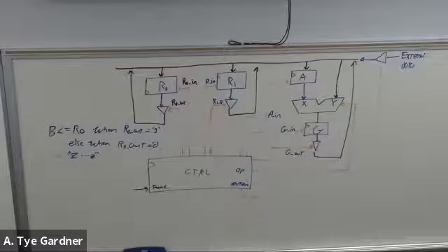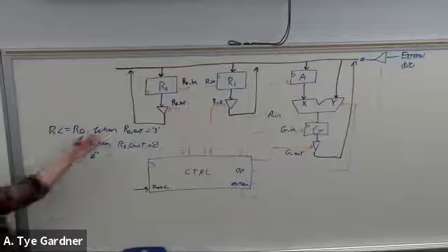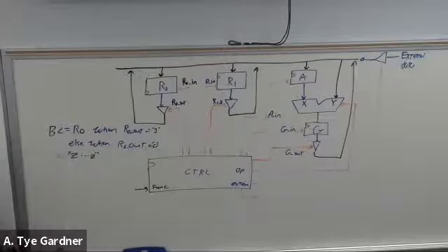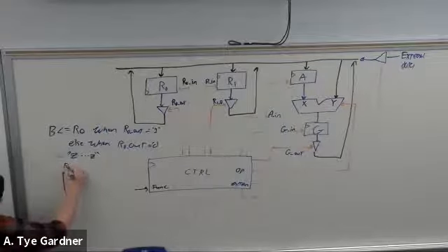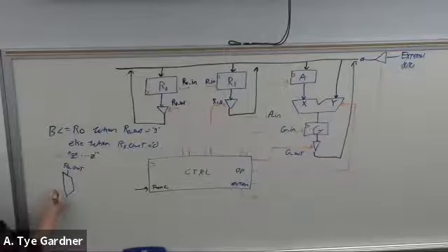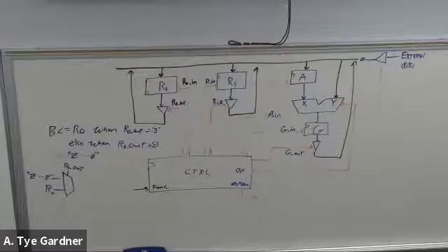Okay, so that then is not really an output enabled bus. That's just a mux that uses R0 out as a driver, and if it picks 1, it uses that R0. If it chooses 0, it takes these. So that's what we're trying to do, more or less.